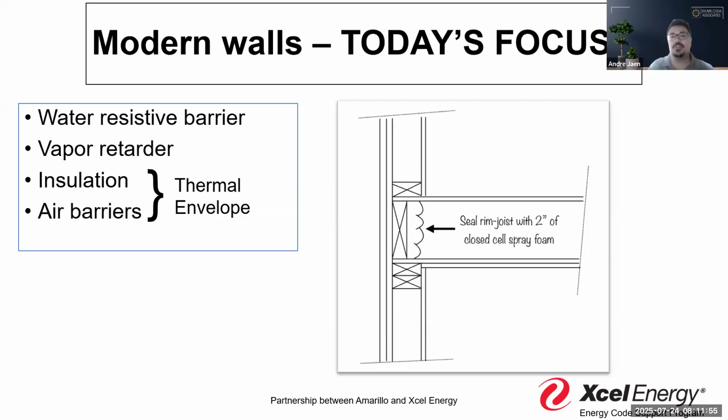They're terrible for air intrusion, right? And so it's one of the places that's specifically highlighted in 402.4.1.1 where we're saying, hey, we really have to get a detail on how you're going to do this and explain your work. Show how you want to do it. And the 2 inches of spray foam is going to be enough to become air impermeable.